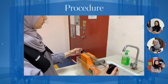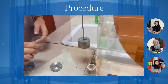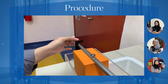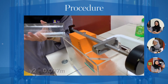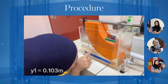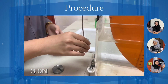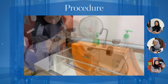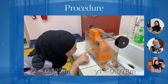For the center of pressure experiment, we use a load of 2.0 Newton. And then we adjust the balance arm and add the water. The water surface to the base of the quadrant was at 0.097 meters. And the distance from the pivot to the water surface was 0.103 meters. Lastly, for a weight of 3.0 Newton, we repeated the same procedure and took the data of Y2 and Y1, which is 0.122 and 0.078 in meters.